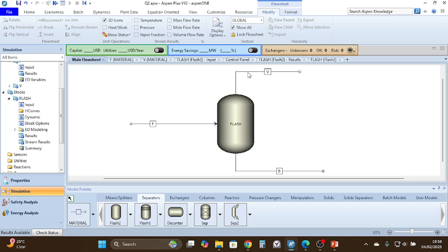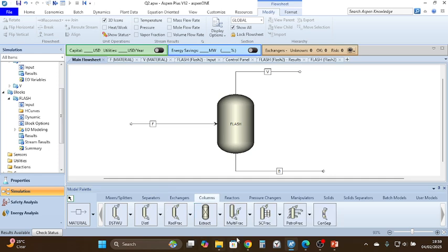In that case, you have to have a good knowledge about the different boiling points of the different components, and there are separators that are present with which you can have multi side draws. We are going to do it in the coming classes. So over here, in these fractionation columns, we can derive multiple side draws depending upon the temperature cut that we want.